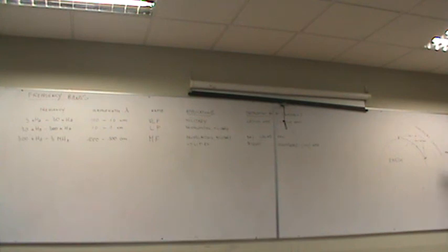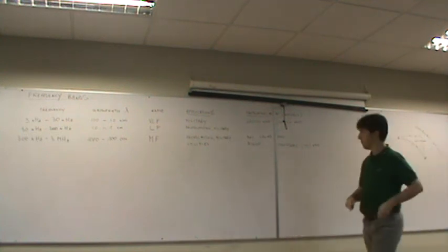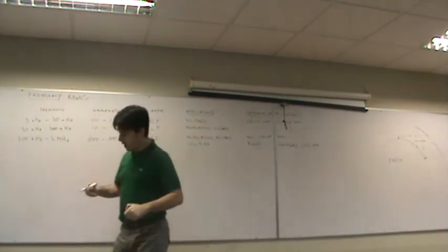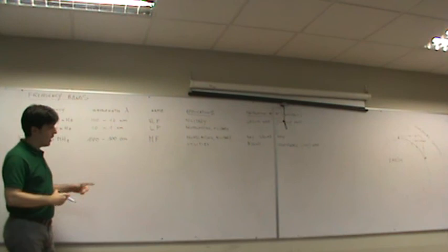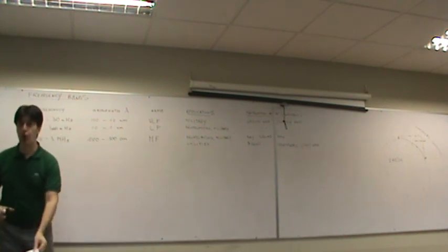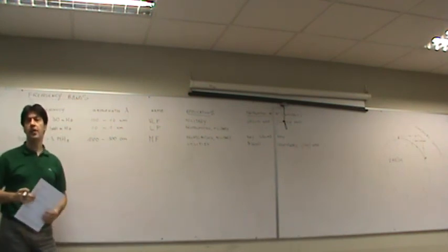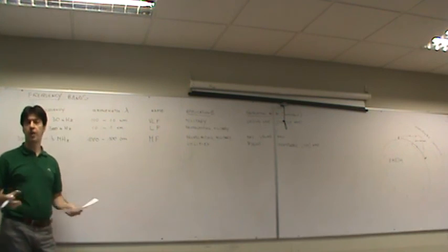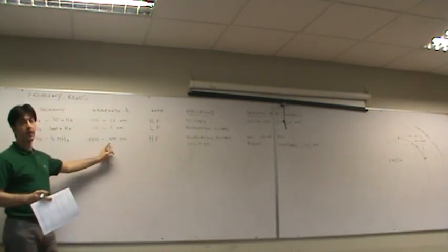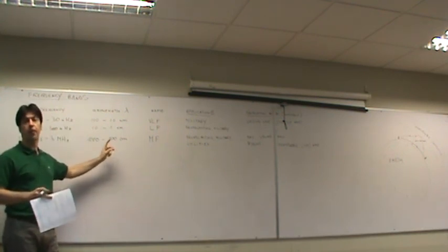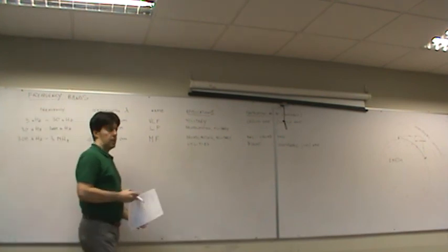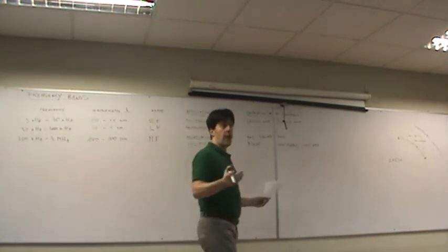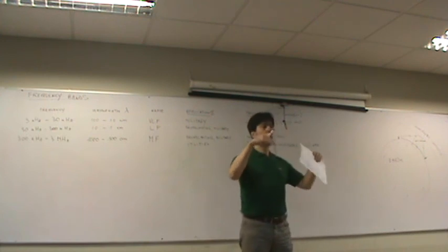That's because during the night you start getting the ionospheric signal. Regrettably, even if the distance that you can cover is very large, hundreds or thousands of kilometers during the night, still the dimension of the antennas would be unmanageable. So we have to move up in frequency.